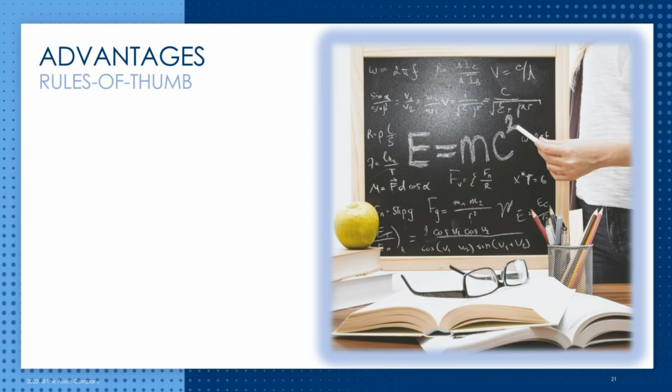The BIM metrics process is a game changer. It allows for powerful short-term knowledge as well as deep long-term insight. We can ascertain useful ratios and rules of thumb for projects. For example, we may ask, what is the expected concrete volume per square foot of building area for a food manufacturing facility in the northeastern United States? If you have done anything similar to this project in BIM in the past, then BIM metrics can give you an answer to such a specific question. And this answer will be continually sharpened as you gain more experience and data points from subsequent projects.